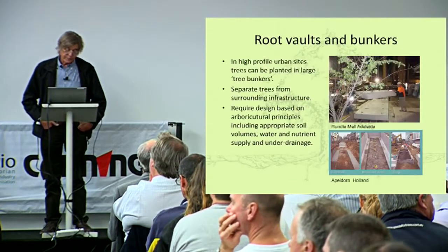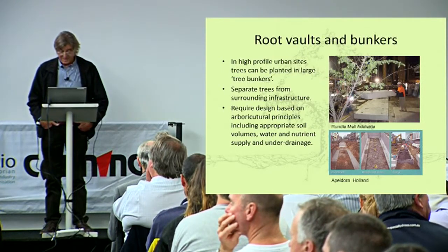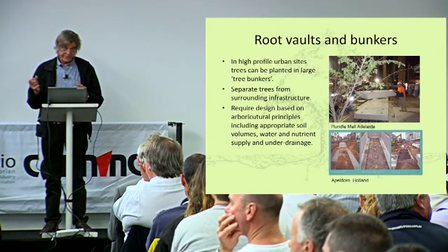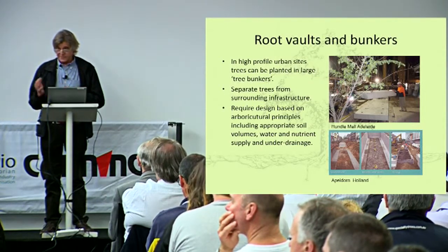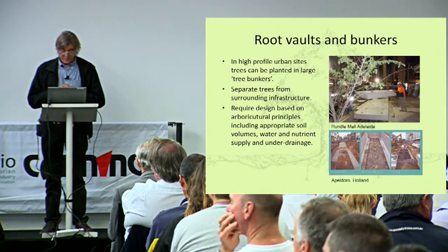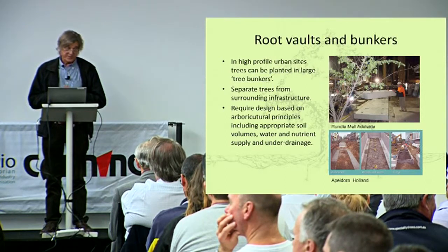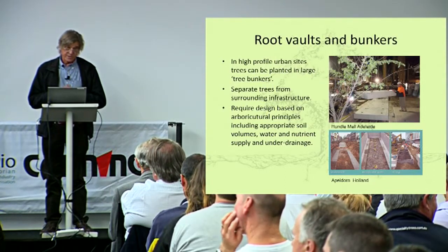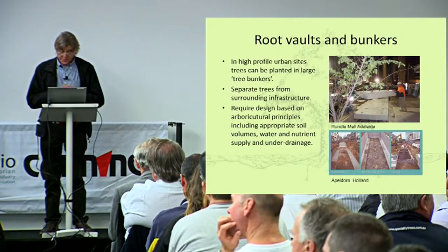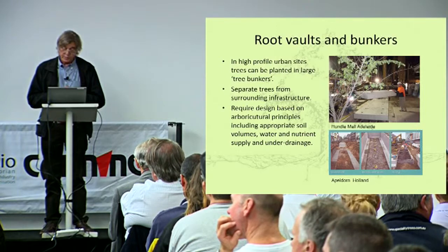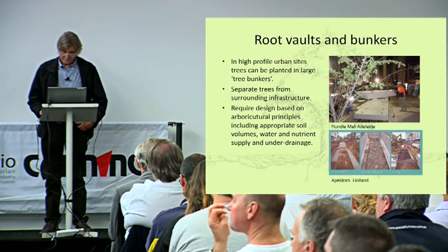Another option is root vaults and bunkers, which Andy mentioned previously. You can create a giant pot for the tree, I suppose, which has a number of advantages in that it separates the tree from the surrounding infrastructure. Once again, it's very expensive, and it requires design based on arboricultural principles of water supply, drainage, etc. Something similar has been done in Adelaide recently in the upgrade of Rundle Mall, where the trees are planted in giant pots.